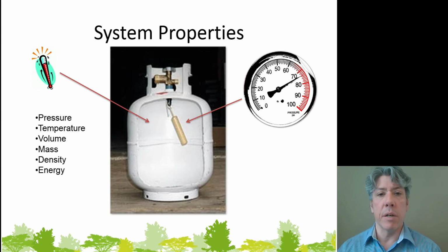Propane tanks actually are required to have a paint on the outside of them that is reflective of infrared energy, and the reason for that is you don't want the pressure and you don't want the temperature to increase in the tank such that the pressure increases also and the tank fails. That can be a problem.